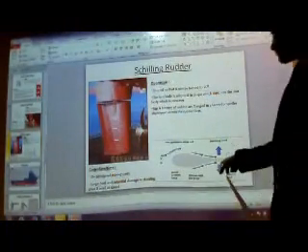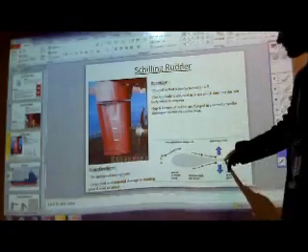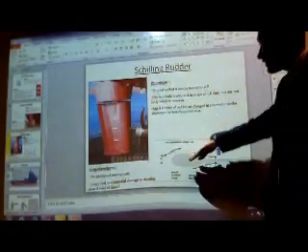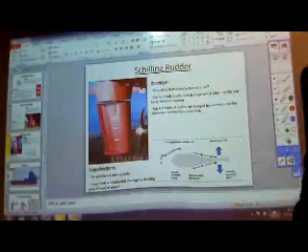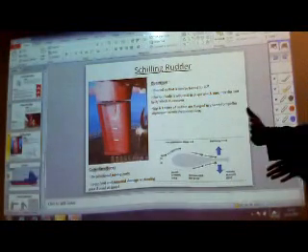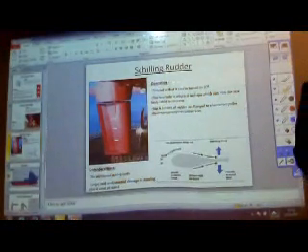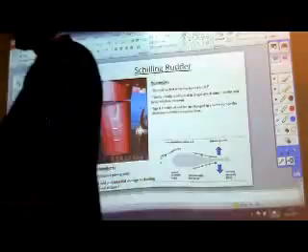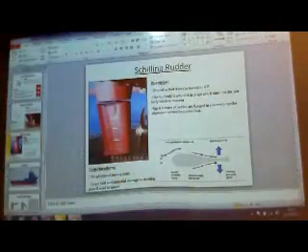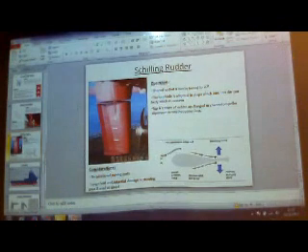What that allows is, especially this curve here, can you see this curve here? When you turn it at higher degrees and the propeller wash is coming, it can throw this and it can then laterally move the ship. Higher motion can be achieved at almost stopped conditions. You can control your vessel's turn to a much greater degree, which you would not be able to do with just a conventional rudder.